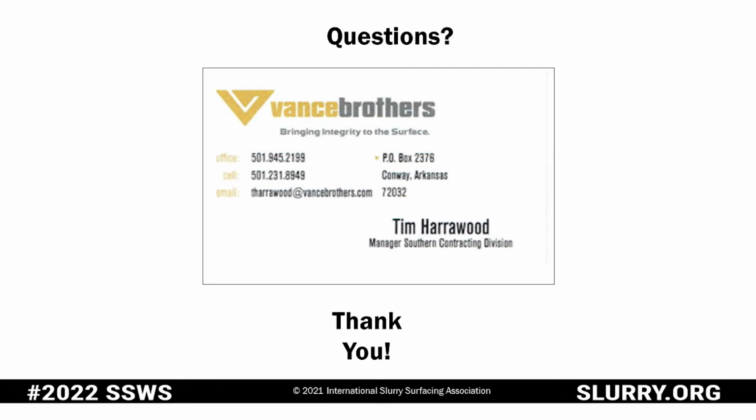Yes, sir. So you mentioned in your tables an optimum of 12.5% emulsion as an optimum number to use. So for states like New Hampshire, where microsurfacing hasn't worked all that well, would you recommend playing around with those numbers, maybe going to 14% emulsion, or using a higher polymer content? We've had a lot of delamination issues in the past, at least that's what I've heard from my colleagues.